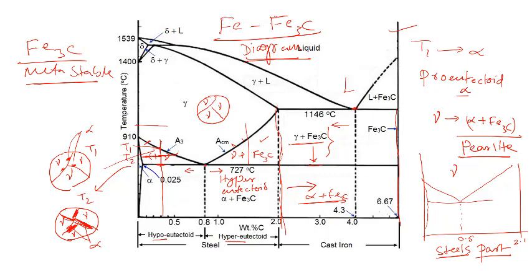That is the steel part of it. But when you say that we have more carbon in it, more than 2%, then basically we are saying that carbon in free form can also form and be present as a phase, as graphite. So then you have to consider a diagram which depicts that condition in terms of the presence of a free form of carbon, right? So then you have to draw this diagram a little bit differently, probably some dashed lines here and there.